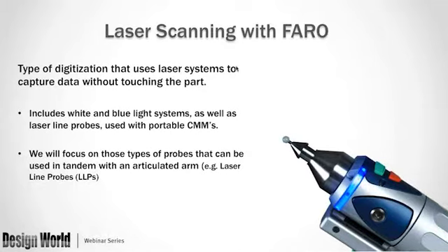There are many types of technology solutions on offer for scanning, which include white and blue light imaging systems. These usually require an independent method to place all separately captured images within the same coherent data set. And this registration is typically done as a post-process, so there's often no real-time feedback for the operator.